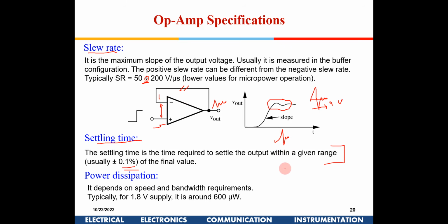If you have learned control systems, you can set these parameters in the feedback in such a way that it is critically damped, underdamped, or overdamped, as you might have learned. If you give a step input and it goes and settles like this, it is known as critically damped. Underdamped means it will overshoot and oscillate, but it will settle down faster than critical. Overdamped means it will go slowly and not overshoot, but it will take a lot of time. Critical damping is an ideal condition, but generally a slight overshoot is okay with us, because it will settle down faster.